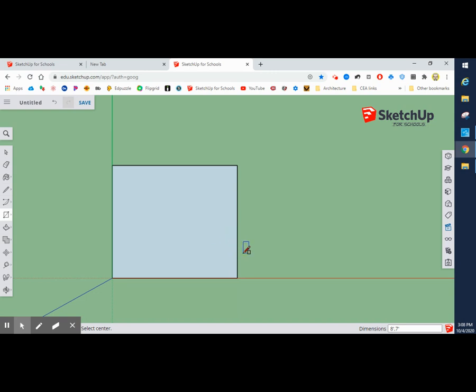All right. Now, we're going to take this a step further than the sketches that we did by hand in our engineering notebooks. We're going to add thickness to our wall. And typically inside of a house, the walls are made out of what we call a 2x4. So we are going to make 4-inch thick walls. To do so, let's come over here. We're going to use the push-pull menu, but again, hit the arrow on the push-pull menu. And that's going to get us out here. We want the offset tool. So click on offset. We're going to offset this rectangle.